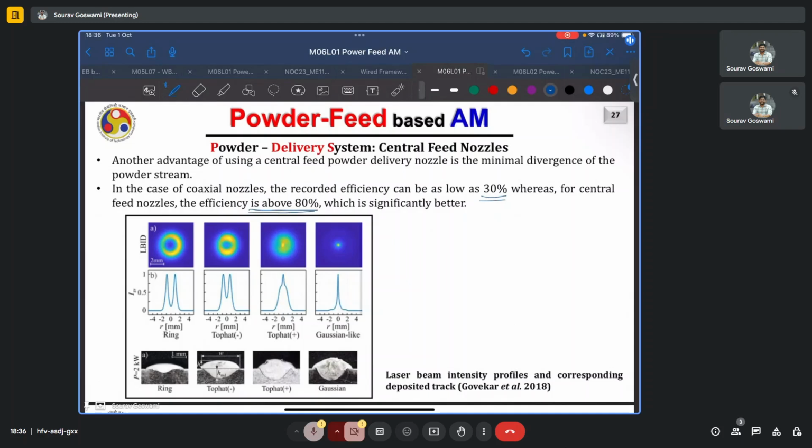In the laser-based active deposition setup that we have here in our lab at IIT Bombay, we have a wire-based setup, which also has a centrally fed wire. In fact, it has dual wire capabilities, and the energy source is in the form of discrete coaxial lasers. So you have 6 discrete coaxial laser beams coming from all the sides, and that also ensures that we have a very high catchment efficiency. Either way, for wire, the catchment efficiency will always be very high because you don't have these powder particles, which can bounce off or other effects. But also this ensures the omnidirectionality of the process because typically for other processes you have the wire being fed from a side.